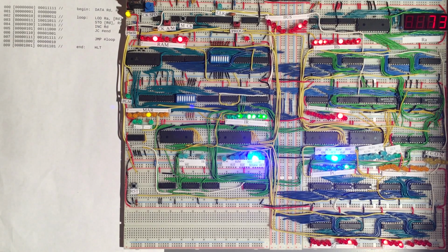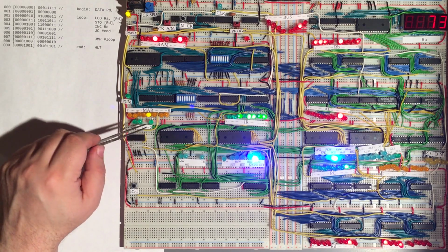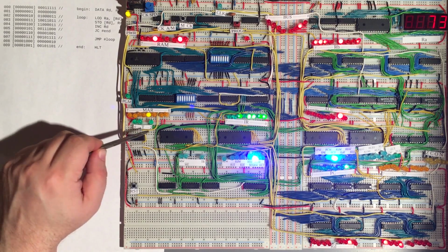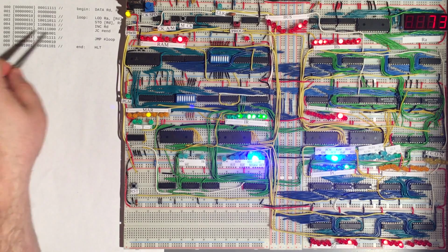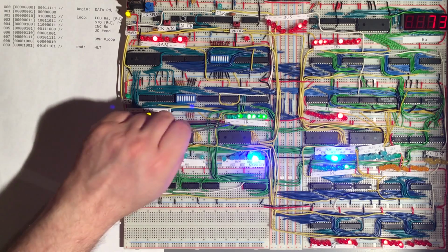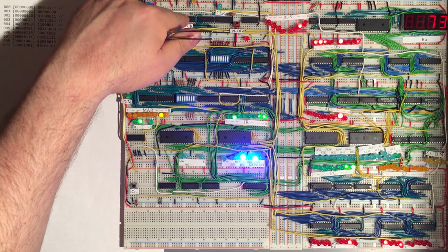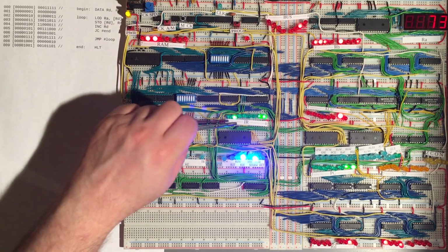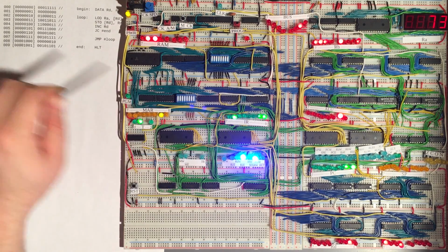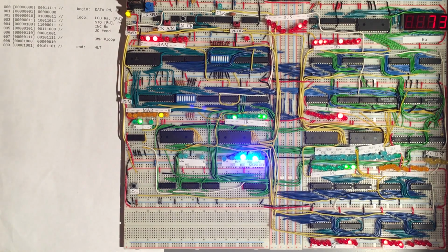And so as for any instruction, the first two signal words, or first two bits of microcode, are the same for time t0 and t1, and they just fetch this opcode and insert it into the instruction register. So we'll go through those very quickly. So that was time t0 and that was time t1, and so now here in the instruction register we have this load instruction, or at least the opcode for that load instruction.